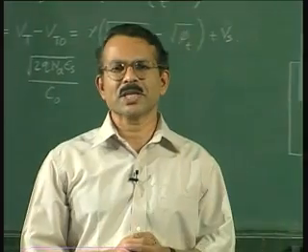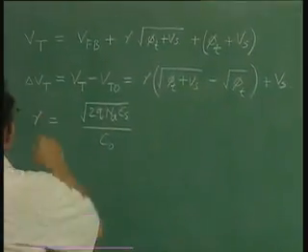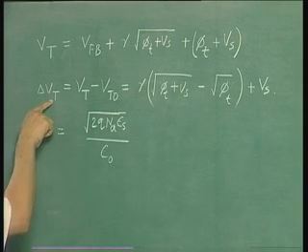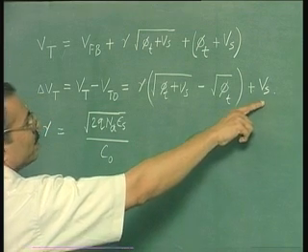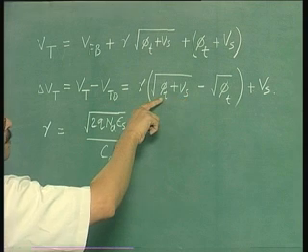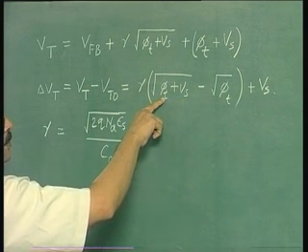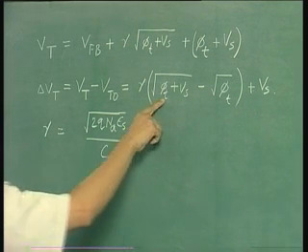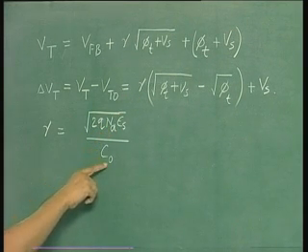Now let us look at the equation that we have derived for this particular purpose. This is the expression for threshold voltage, and this is the expression for change in threshold voltage. So you find in the expression for change in threshold voltage, we have only the source voltage Vs and the voltage drop in the semiconductor at inversion when the source voltage is 0, that is phi t, and the parameter gamma, which contains the doping level of the substrate and the oxide capacitance.